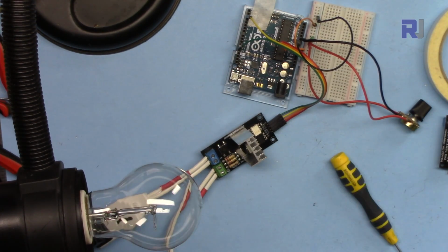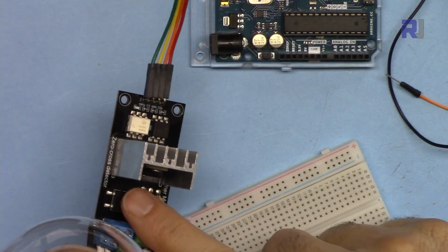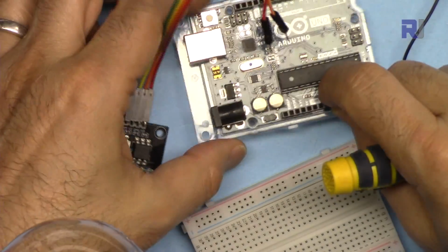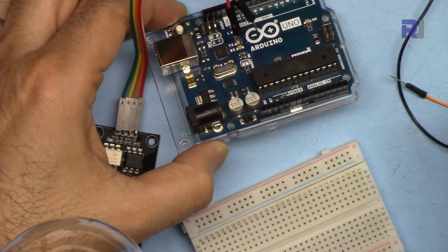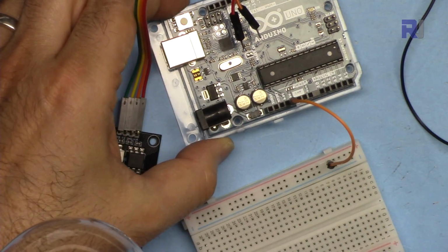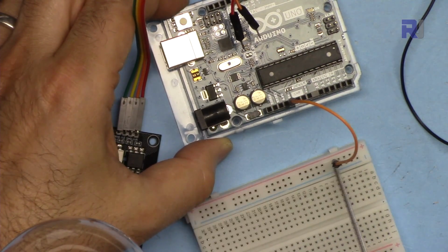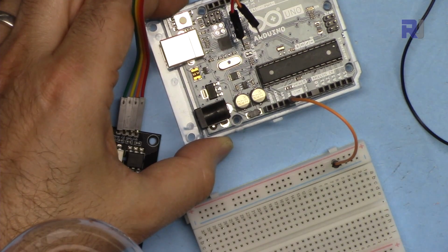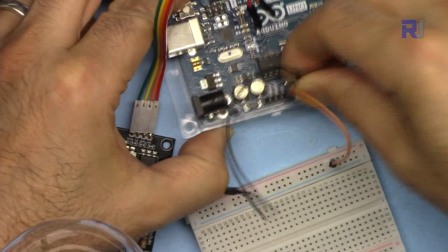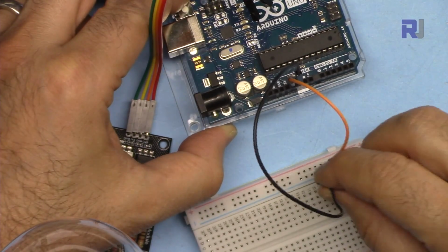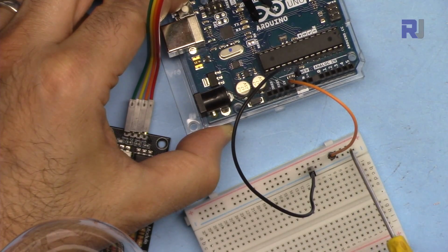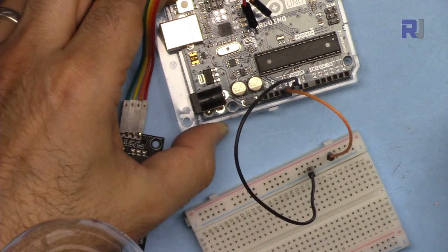Now let me explain the wiring. Because I needed 5 volts for this and 5 volts for this potentiometer, and my Arduino does not have extra 5 volts, I've connected this wire from 5 volts to one point on this breadboard, the red. So this is my 5 volts now. All of these are connected, and then one more wire for the ground, and this is connected to the second line here, where now this blue is all my ground. So I have 5 volts and ground available here.